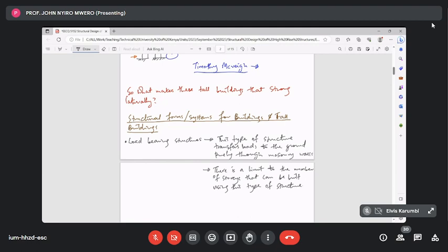Here in Kenya, we have an old earthquake code, which I will introduce to you in the coming sessions, and I think it generally limits masonry buildings to about 4 or 5 stories. So I will just put this here as an example, 4 stories.